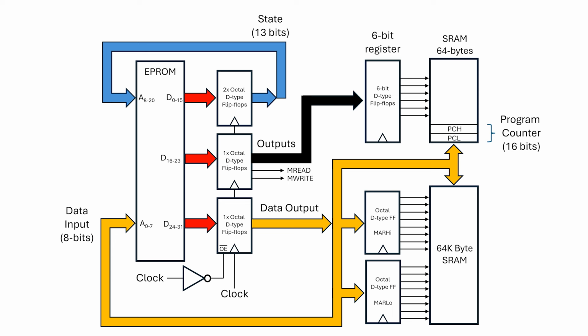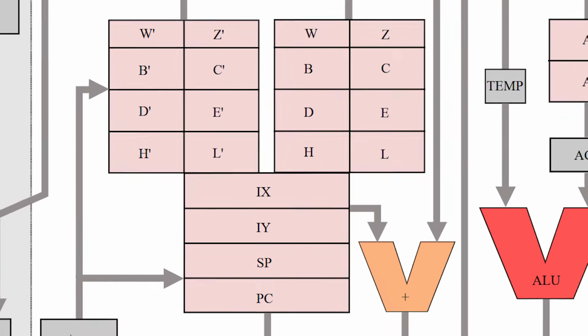The program counter variable is great for stepping through code, but I also want to be able to read memory locations without upsetting the program counter. For this, I'm going to add more variables into the static RAM, specifically a 16-bit effective address variable. The state machine then gets to decide whether the program counter or the effective address is copied into the memory address registers. We can even add more variables into this memory, such as an A register, a flag register, and hopefully you can see where I'm going with this.